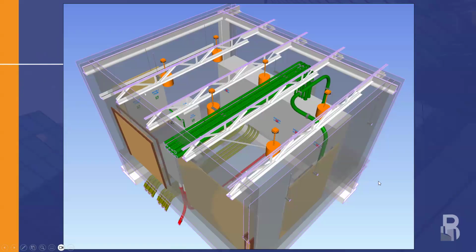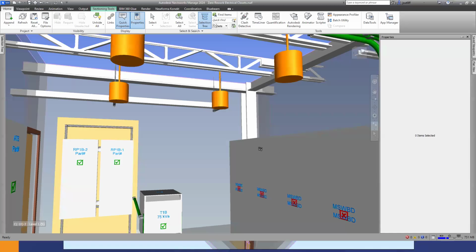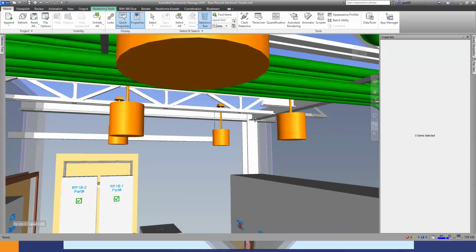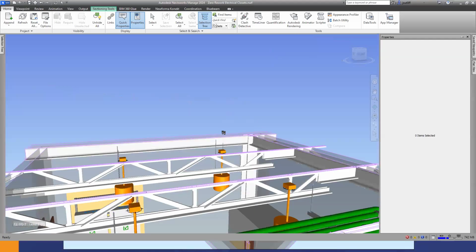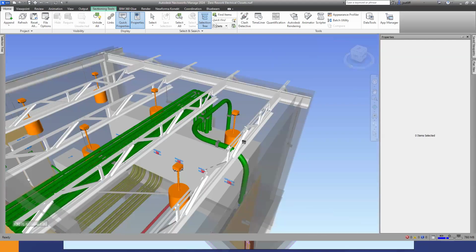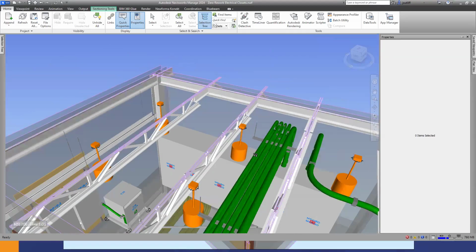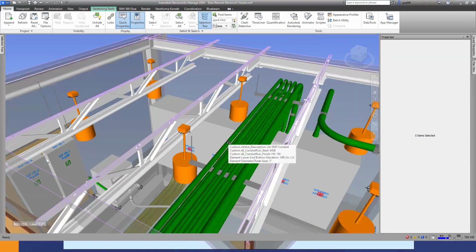The last thing that I have here is our flying of the model, having Navisworks available to the field team and having them know how to use it, or flying this with the shop, is an important aspect as well. And the information and the data that comes along with this, because we're putting the I in BIM here, we can have this easily accessible for our field teams with the quick properties in Navisworks specifically.